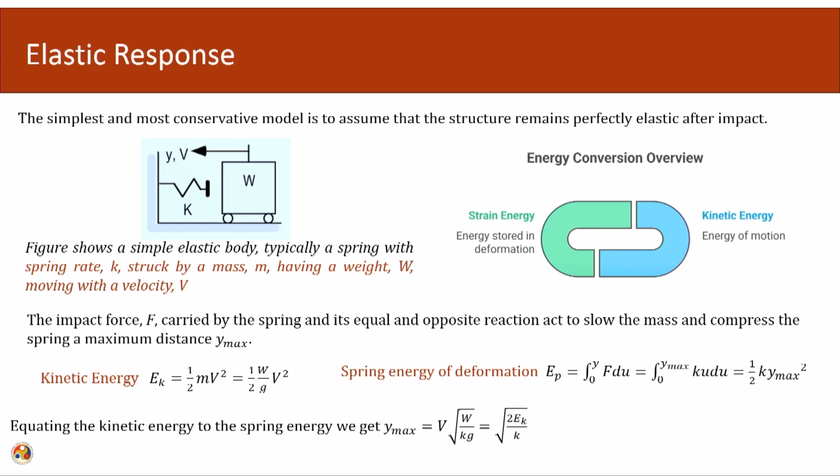So, elastic response. Now we will model the body using a very simple approximation. The simplest and most conservative model is to assume that the structure remains perfectly elastic after impact. It means that the force versus time as well as deformation versus time graph is symmetric. So, what we are doing is representing our body using a very simple model.